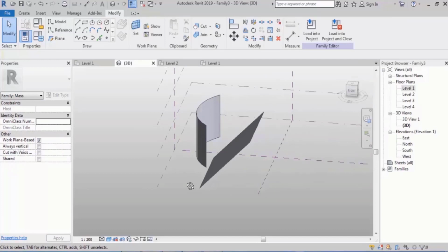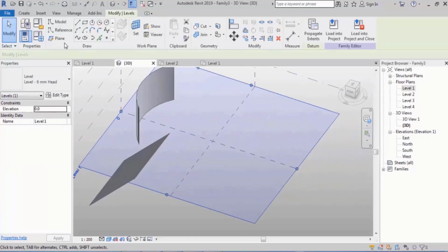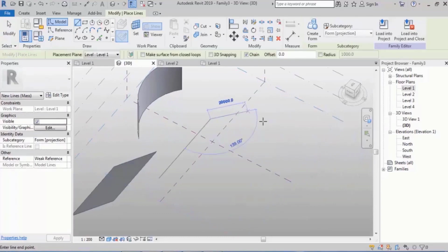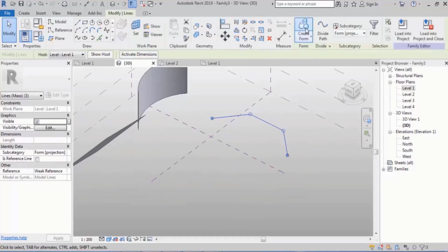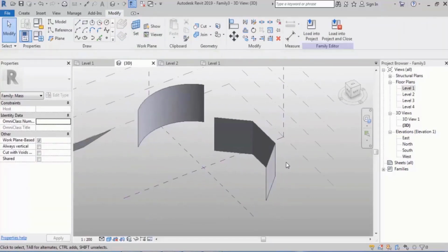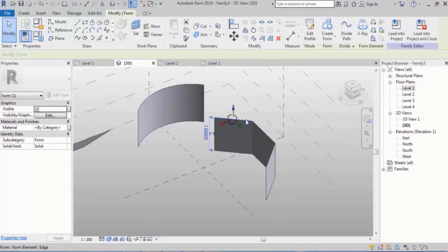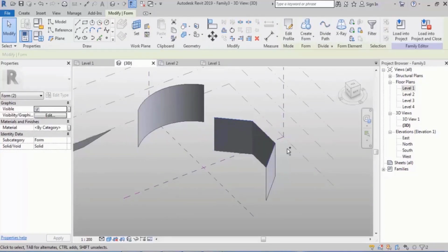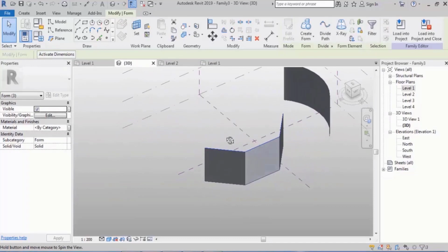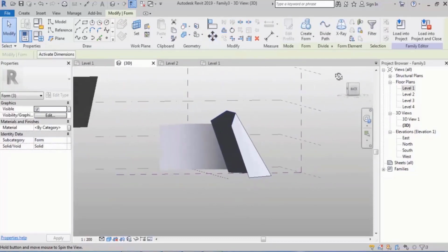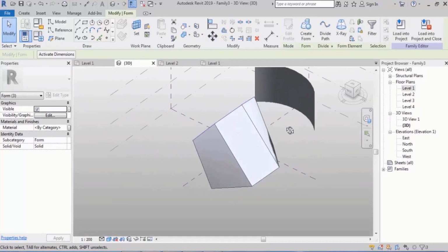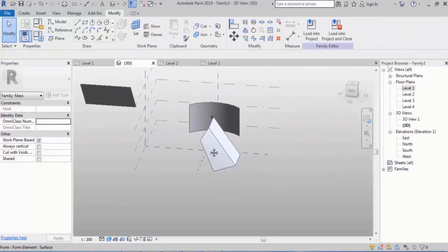change it to this. I always insist that you should not design the body of a building using model in place. It's because of this. It's so much more difficult. Or for example, let's just imagine that we have something like this. It comes up. Now you can, for example, select them like this and then move it. You see that? We can do many things with it.